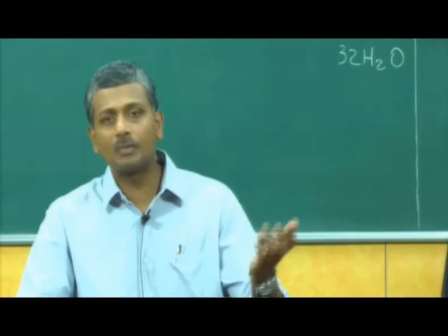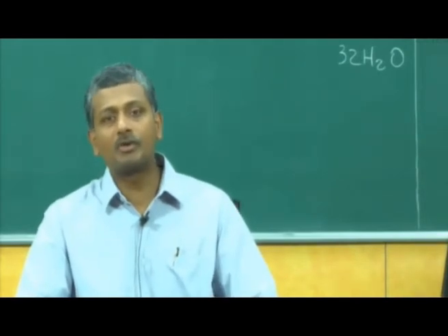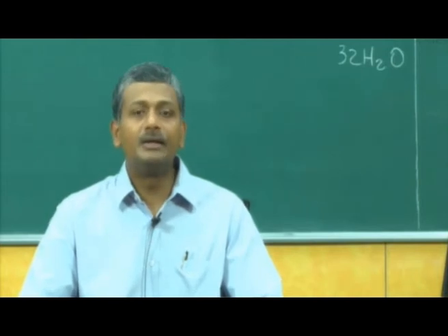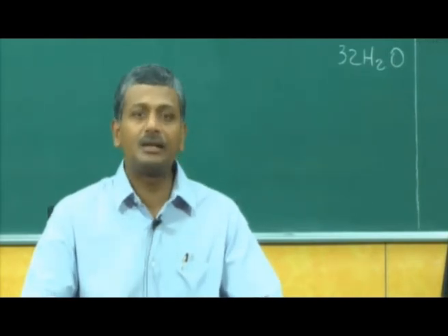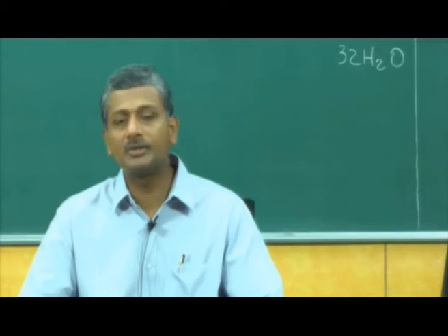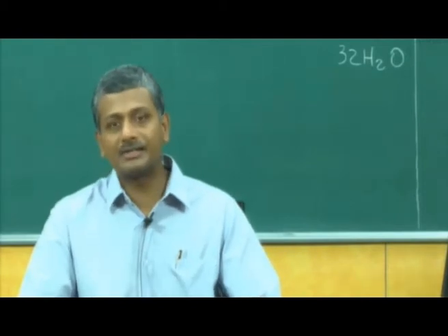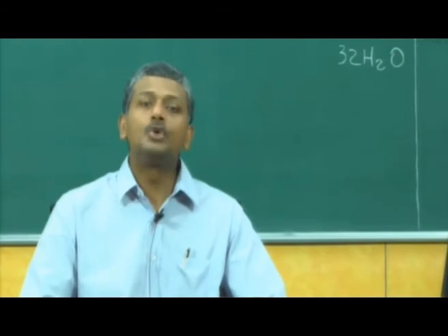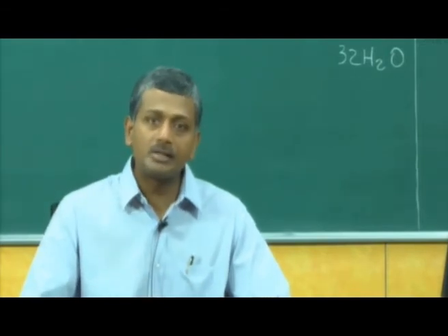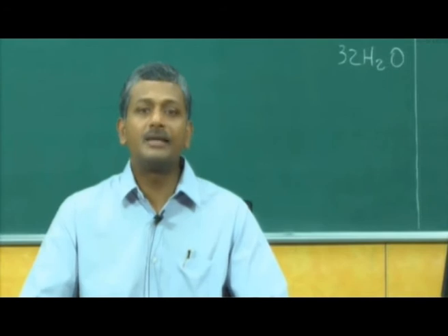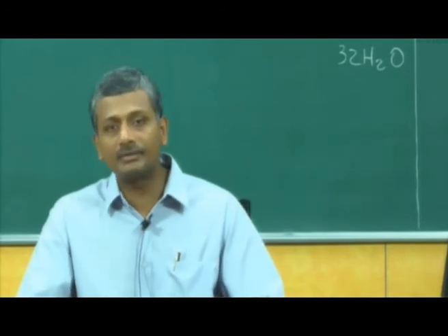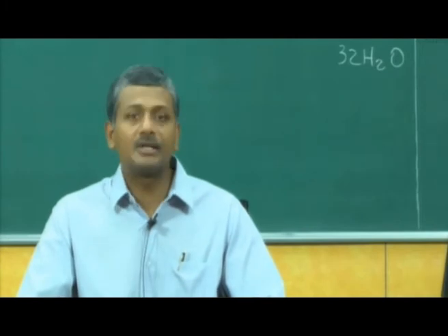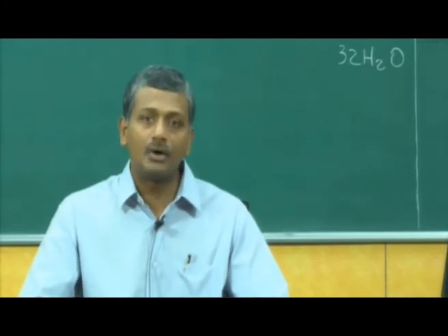I am not going to go into the polymorphic forms because polymorphism again is a subject that requires a lot of debate and understanding. We have not really covered that level of detail in our discussions in the last two chapters. So let us not talk about that at this stage. In general, the reactivity is associated with the fact that you have your cement particles present in an irregular form, and secondly that you have several impurities like impurity oxides that I showed you in the last class that are also present that contribute to this high reactivity of C3S.